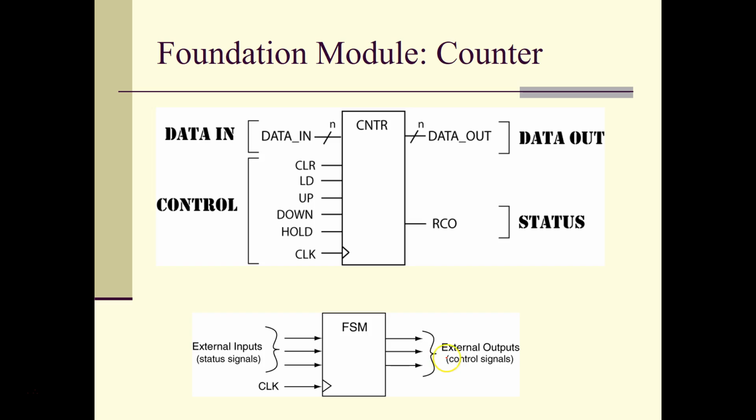Okay, remember this is the FSM down here. The outputs of this FSM are control signals. It's going to be connected, generally speaking, to these control inputs on the counter. The status output of the counter is going to be an external input to the state machine.